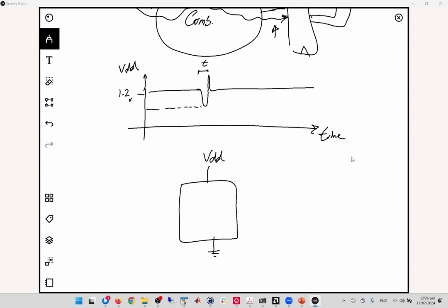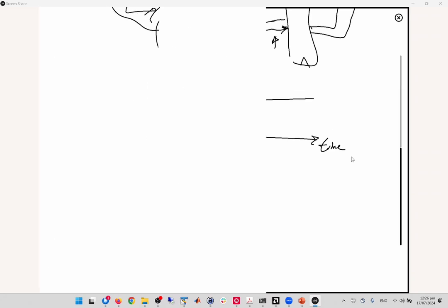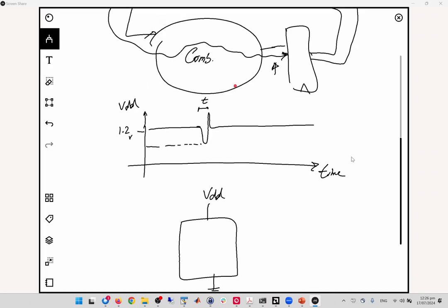Again, some values inside the circuit will not work correctly because when you decrease the VDD, the gates in the combinational circuit become slower, because their speed depends on the VDD. Of course, from one point, you cannot increase it, because if you increase it above the nominal voltage, there is no guarantee that the circuit stays alive.